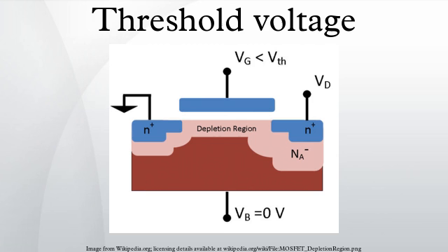Dependence on oxide thickness. In a given technology node, such as the 90 nanometer CMOS process, the threshold voltage depends on the choice of oxide and on oxide thickness. Using the body formulas above, γ is directly proportional to tox, which is the parameter for oxide thickness. Thus, the thinner the oxide thickness, the lower the threshold voltage. Although this may seem to be an improvement, it is not without cost. Because the thinner the oxide thickness, the higher the sub-threshold leakage current through the device will be. Consequently, the design specification for 90 nanometer gate oxide thickness was set at 1 nm to control the leakage current.